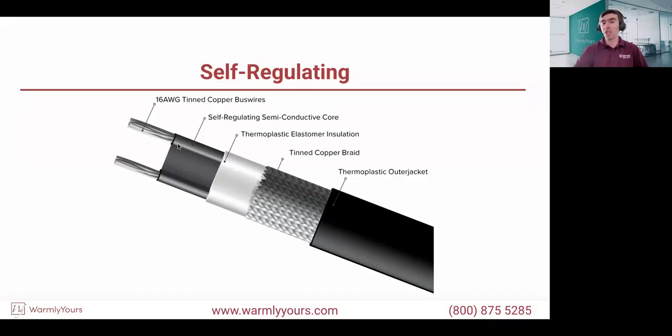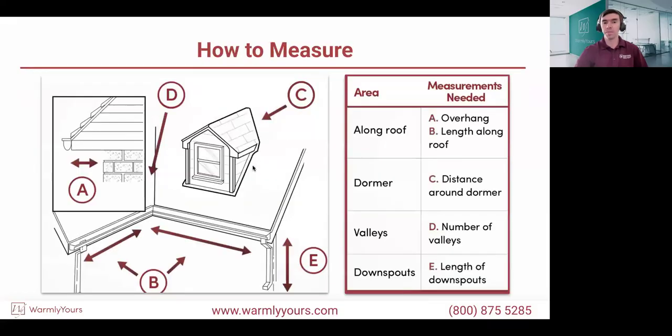So again, I'm going to call it an eco-conscious product selection, because you're really having the product do the job for you by self-regulating what needs to be heated in the given moment. And at the end of the day, it's just heating very economically. It can be overlapped, it can be crisscrossed, because the cable will react to itself and never overheat. So again, great product selection for medium to larger commercial applications and so on. Excellent.